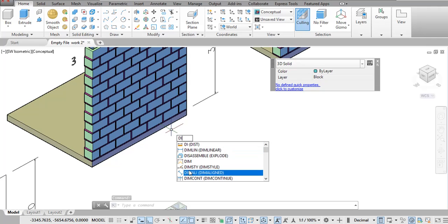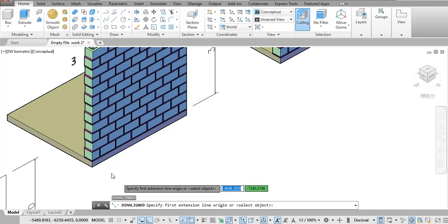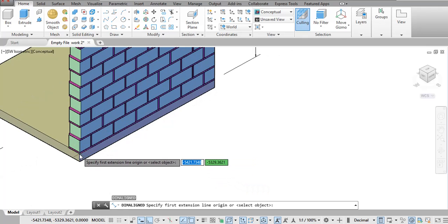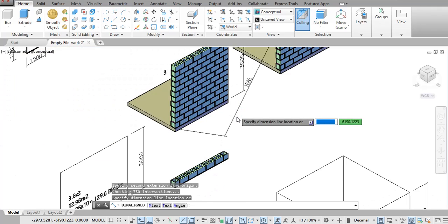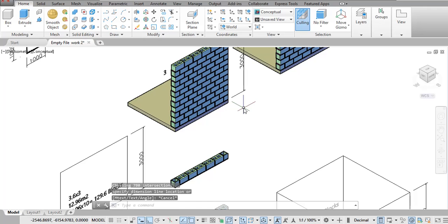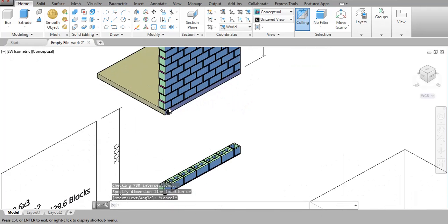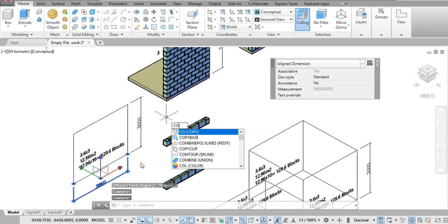The dimension we need is not the linear type, but the dimension of our line. That's what we need. So we can click to know what the dimension from here to here will give us. Why we are facing this is because our UCS has not been set to give us this, but we can as well copy from existing.